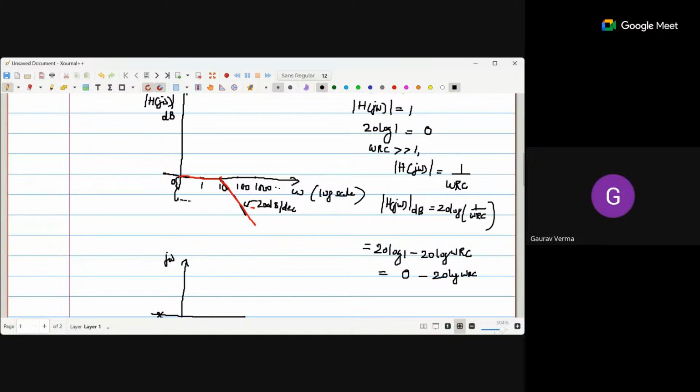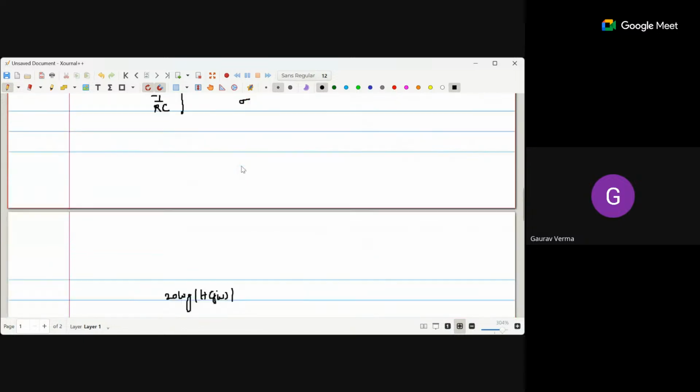Okay. So the projection that we are seeing on the x-axis now is the cutoff frequency. Yes, you take the 0 dB line, you subtract 3 dB, so that refers to the minus 3 dB, and projecting that onto the x-axis will give you the cutoff frequency. Okay, it's clear now. Thank you.